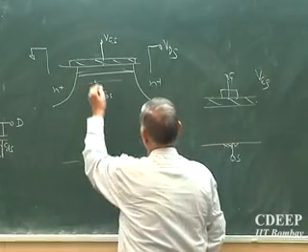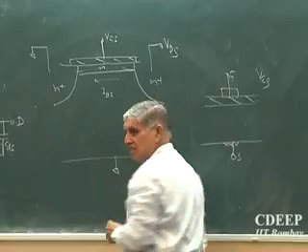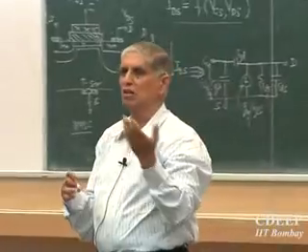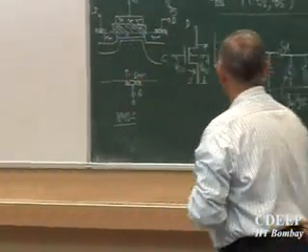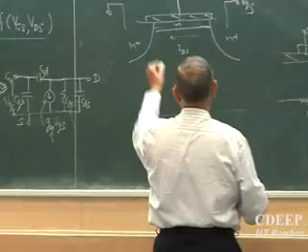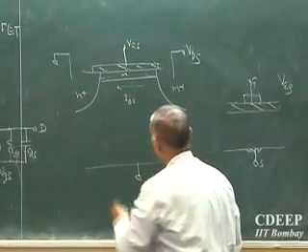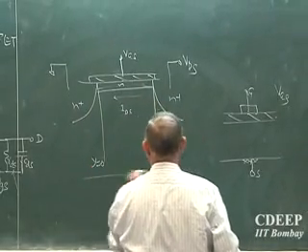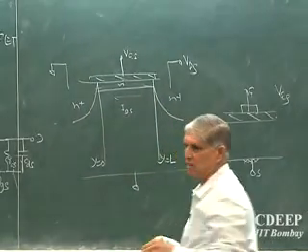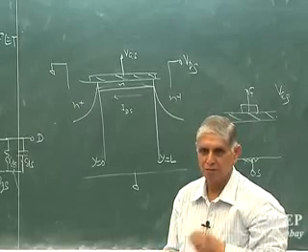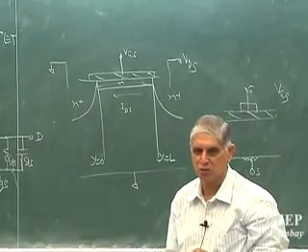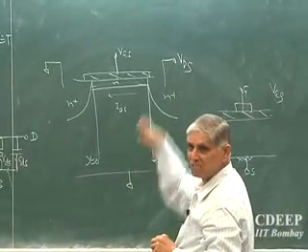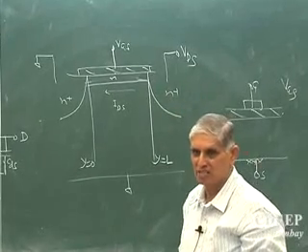I figure out that this is an N-channel device. There are a number of electrons per cc in this channel, equivalent to some sigma. Now this means there is a voltage drop from this terminal to this terminal. So this I call y equal to 0, and this I call y equal to L. The y direction is this direction, so y equal to 0 to y equal to L is the channel length. Width is in which direction? Into the board, in that direction.